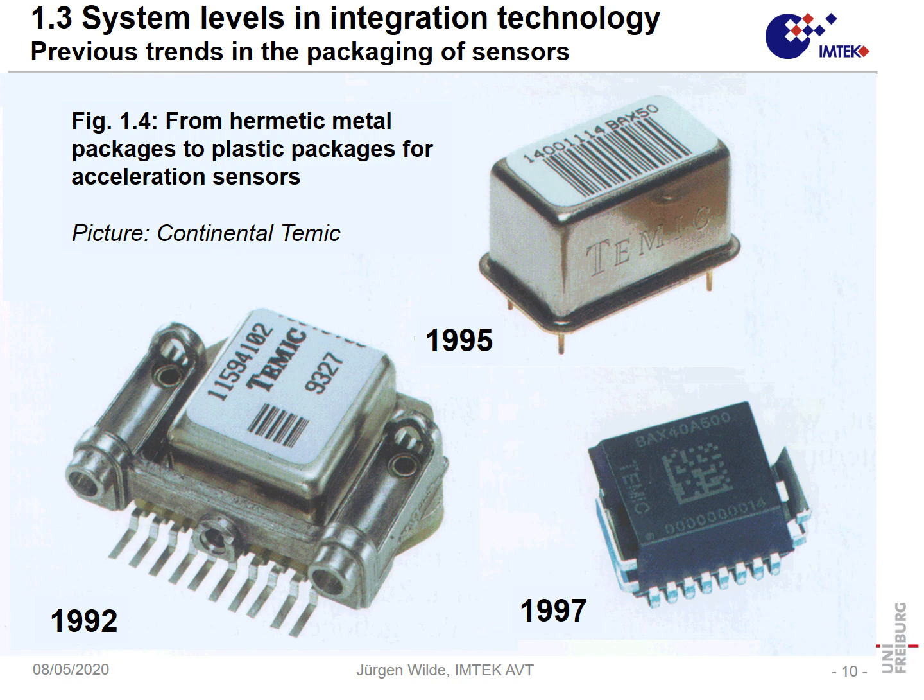What you can also see at that time, we had a barcode, but after a few years, all of that was changed over from a device which has pins and a metal housing to a plastic housing, a so-called surface-mounted device. So we have no longer holes in the printed wiring board. We can just mount it on a printed wiring board. We found out that that is sufficient for crash detection.